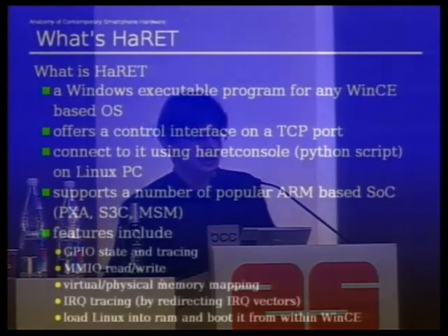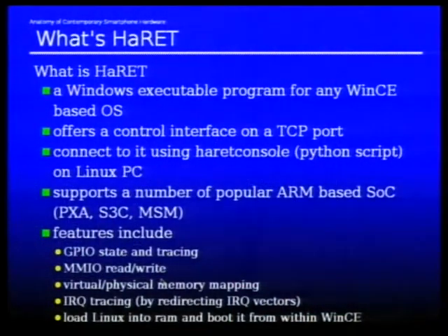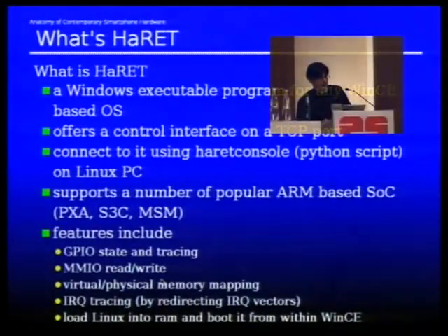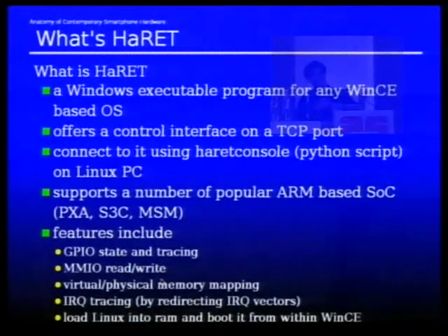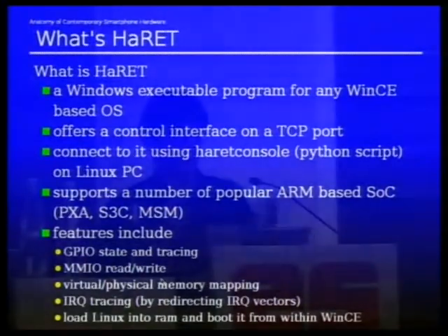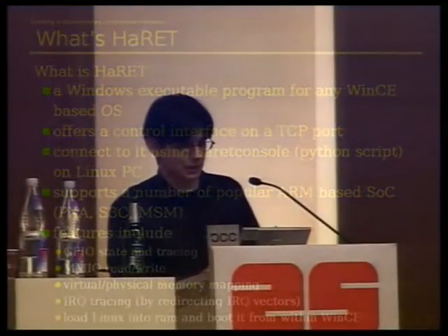The other approach, which is not as hardware-centric, is a hardware reverse engineering tool. It's an executable program that you can run on Windows CE devices, and it has a control socket on TCP. You connect to it from a console program on your Linux box or other box. And then basically you can do things like give me one event for every interrupt that you receive, and then you get all the kind of interrupts. And you remove the ones that are noisy, and then you start pressing keys or sliding the slider, switching on and off your backlight, your Wi-Fi, your GPS, and you try to see what kind of GPIO pins or interrupts happen, or what happens on the device when some kind of external event happens. So you can learn more about how the device works.